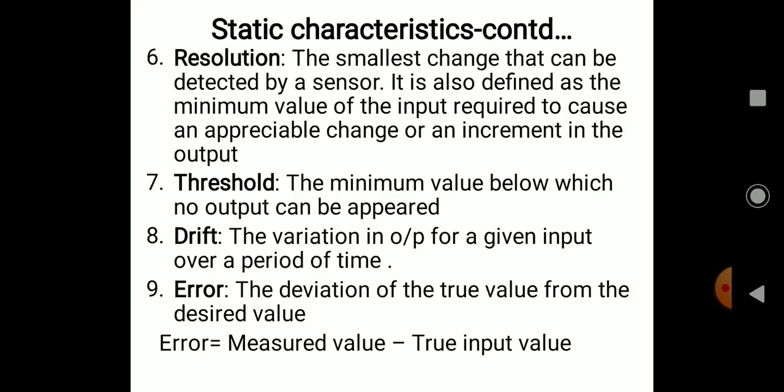Then if you keep it between the jaws, or measuring anvils, of the micrometer, you'll be getting 10.01 or something, or 9.99 maybe. So the measured value is 9.99 and the true value is 10 mm. The actual value is 10 mm, that is the standard value because we have taken a standard cylinder. So we are getting the error of the measurement.